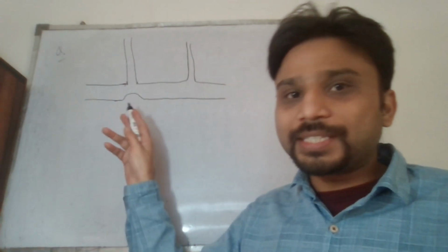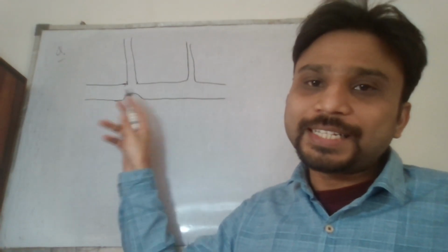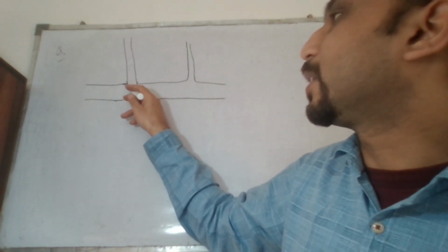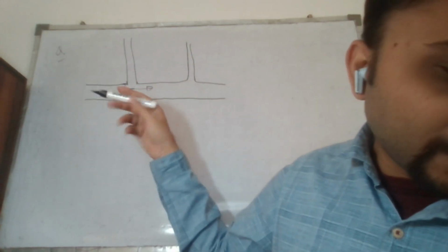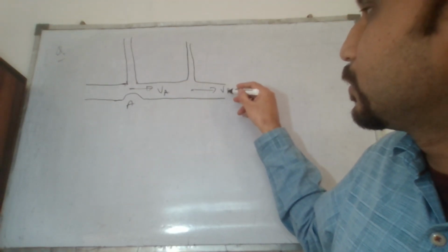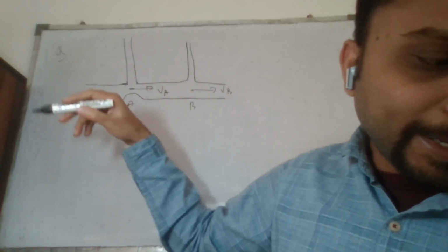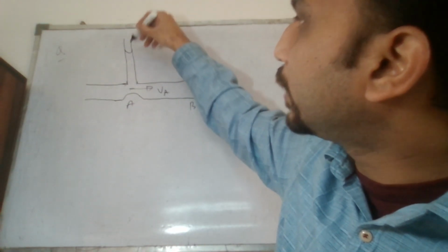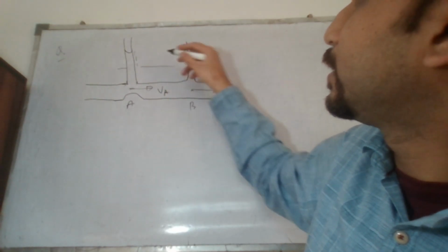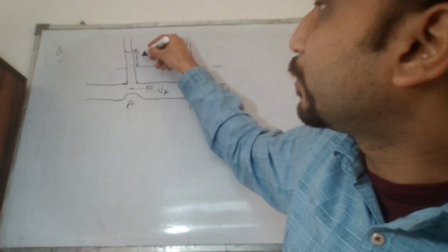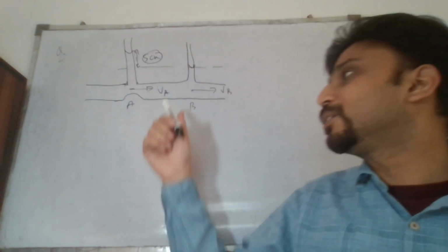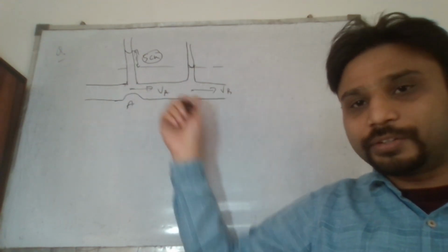So you would guess, yes, because there is a constriction, the pressure would be less at this point, velocity would be more. Velocity would be more at this point, that we know. So let's say this point is A. Here velocity is VB. It is given that the height of the fluid at this point is more than the height of the fluid somewhere here by a distance of 5 centimeter. So basically, this is the rho g y term which contributes the pressure difference.